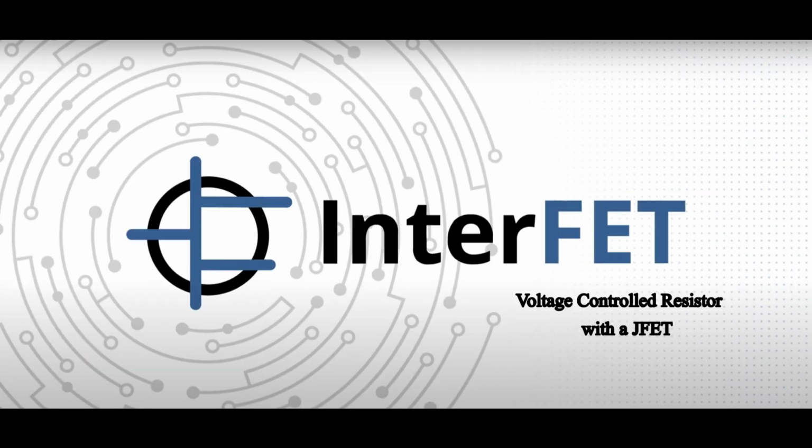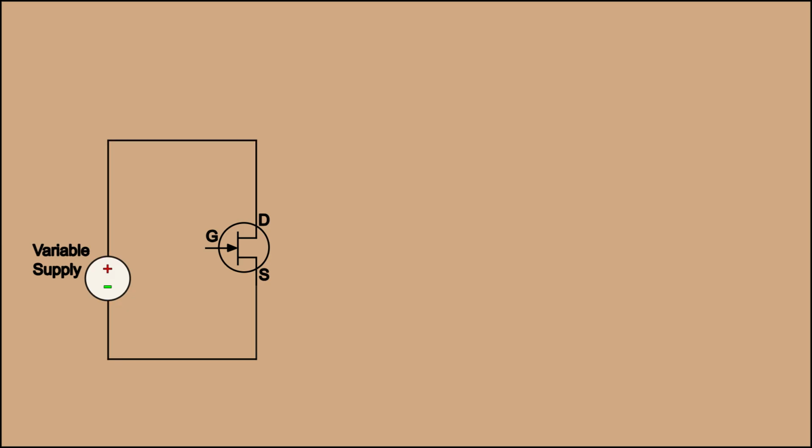In this video, we will see how a JFET can be used as a voltage controlled resistor. Let's form a circuit with a JFET, shown here, and a variable power supply. By connecting the positive connection of the power supply to the drain of the JFET and the negative of the power supply to the source, we can create a current in the direction shown by the arrow.